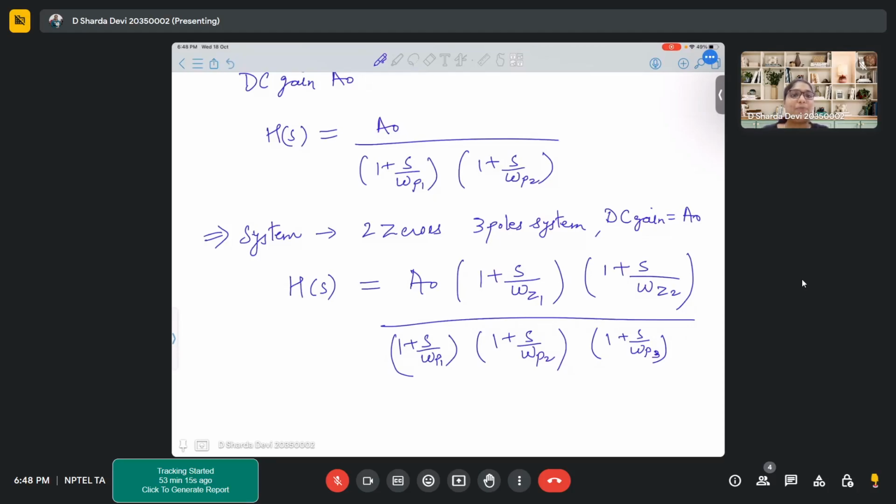Ma'am, by drawing a Bode plot, suppose first you encounter the pole first. In front of a DC gain, you start with the DC gain, say about 40 dB. Start with the 40 dB, and then you encounter the first pole.